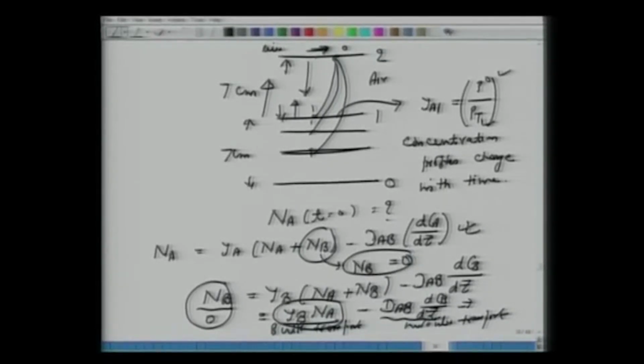So we do have a gradient of air which goes like this in this diffusion length between the top of the tube and the top of the ethyl acetate surface. But at any instant, whatever amount of air diffuses by molecular diffusion is balanced by this bulk transport in the opposite direction. So this diffusion is balanced by this bulk transport, and we have stagnant air in the medium.